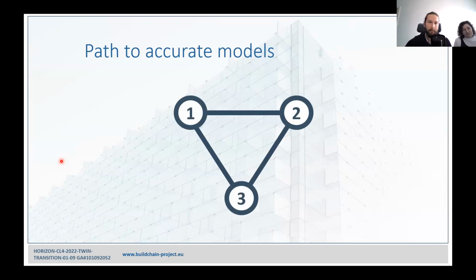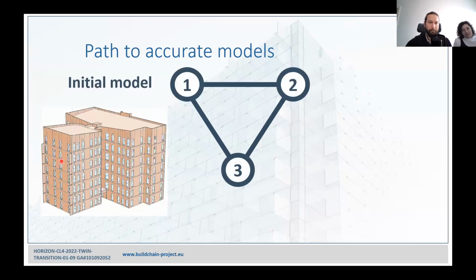And this is done in 3 steps. The first step is to create the initial model. This initial model is done with finite element models, with commercial software, using all the documentation that we have on that building. And this is our best engineering judgment prediction on model properties. And this is also what design practitioners can do. And at the end, what we get is model properties. Those are natural frequencies and mode shapes, about which Uros talked about.